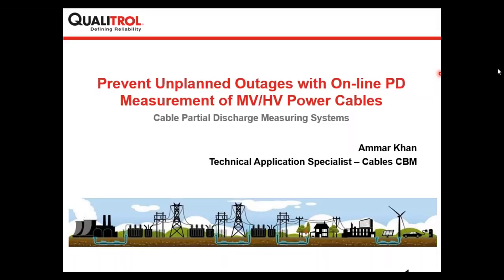If the defect is inside the insulation, then it will become an internal discharge. If the defect is on the insulation of the power cable, then it will become surface discharge. And if there is a stressed region because of some protrusion or impurity near the conductor, then it will lead to corona discharges.